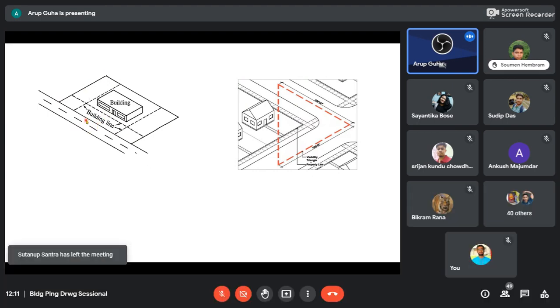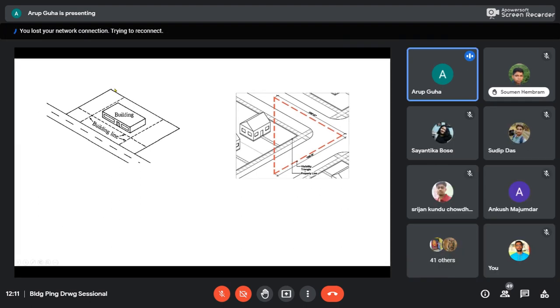Here there should be some diagonal clearances, because if there is a road here, then if this person turns left or right, he must have a view of what is happening over here, otherwise an accident will happen. So for your benefit, the corporation or those booklets will say that there should be no hindrances in this place, so you can have a clear cut view. Setback lines.